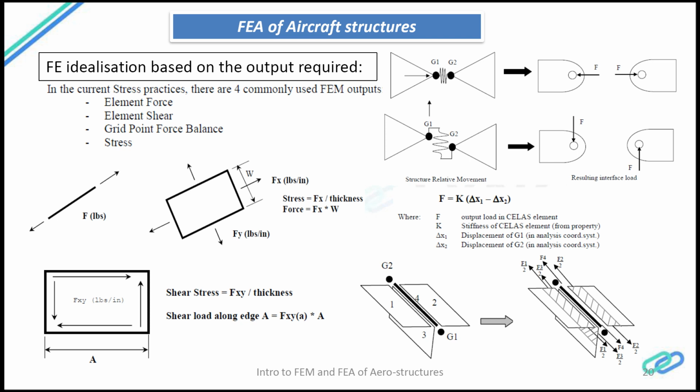So moving on to the next slide, we have some of the idealizations and some of the equations over here, which I have put in just to show you what kind of forces or what kind of loads each of these elements take. First one is the simple 1D element, which is the rod element. It takes only the axial forces.